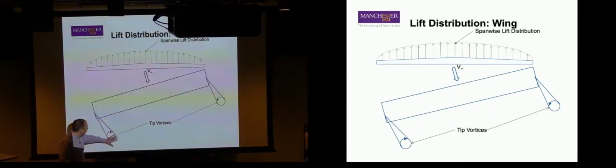You're right. To get that lift, one of the characteristics is we have to have a pressure differential. The pressure has to be lower on the upper surface than on the lower surface. That's how we resolve those forces, right? If they're the same, you put them all together, add them up, the sum is 0, you have no lift. If there is higher pressure at the lower surface than the upper surface, two things must happen.